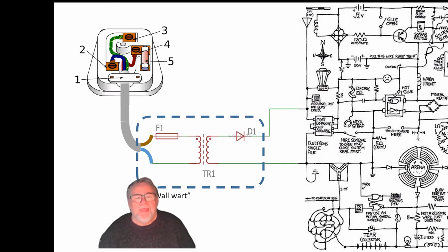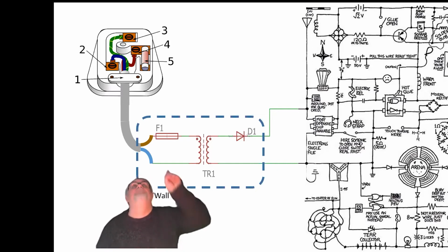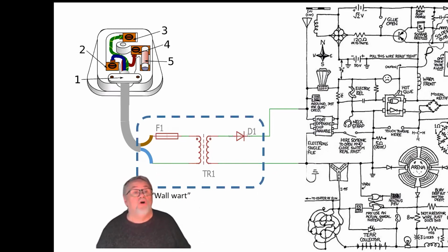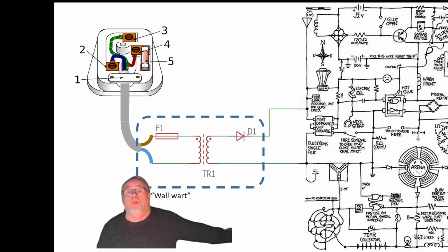And that circuit is driven by a wall wart. And the wall wart has a fuse in it, F1. And that fuse, F1, is only there to protect the bit of grey wire above my head. Right, that's what F1's for, that bit of grey wire there. And that's all. And the fuse itself, the cartridge fuse in the plug, which has got a 5 pointing at it, for reasons that I can't remember, I think there was drink taken when I was doing this slide, the cartridge fuse is there to protect the wiring in the wall.